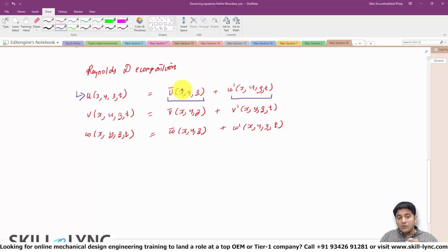All right. Well, how far are we averaging? Well, we are averaging it for a time that is much larger than the turbulent time scale. Why are we doing this? Well, if you take a look at all of your engineering quantities, this is the quantity that people are interested in. The averaged quantities are great, but say that you're simulating flow over an airfoil, you need the time averaged drag coefficient, correct? Which is what is interesting to you. If you have the instantaneous velocity components, you would still have to time average it, right? And that is the motivation for Reynolds decomposition.